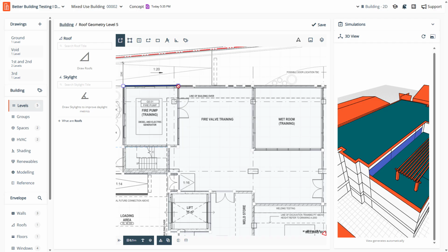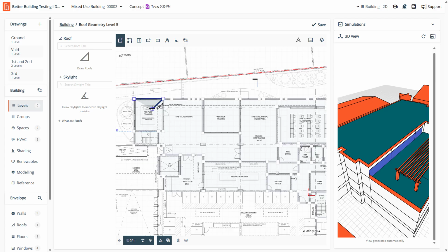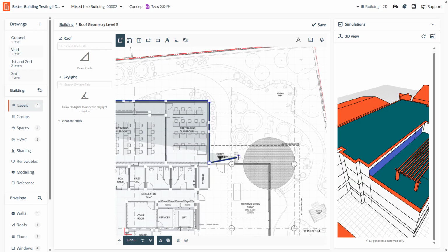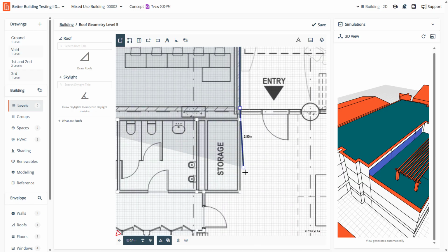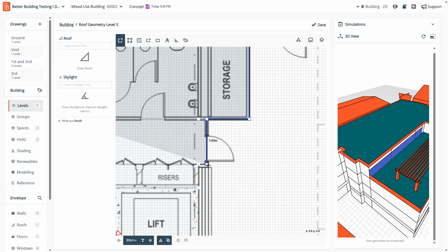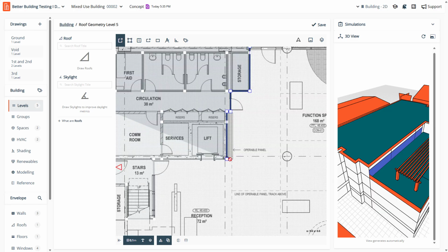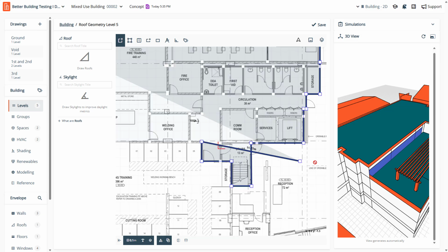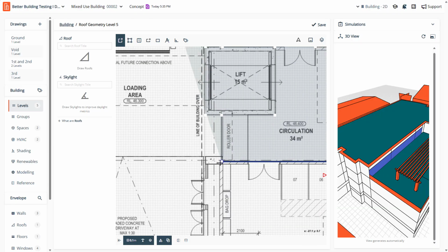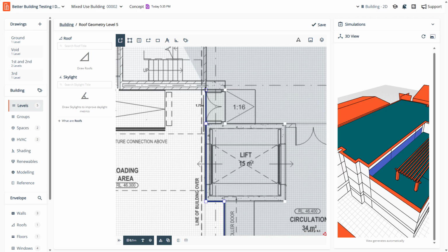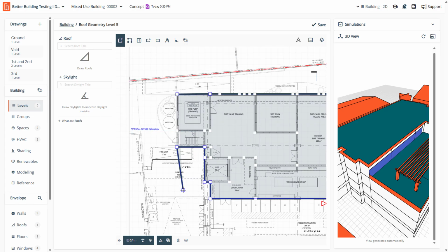Okay, so typically you want to go ahead and connect to every node. And I say typically, that's if you're not drawing straight and you're not being really cautious about your drawing. If you do not connect to each node, please expect to have issues. Now, because I'm somewhat of an advanced modeler, I don't need to do that because I know everything is nice and straight. But if you do have problems, connect to each node until you're confident that you don't need to, and it's not going to cause any errors.